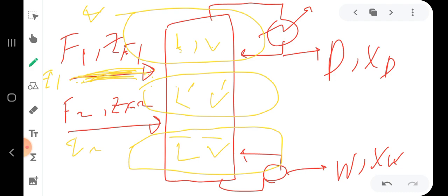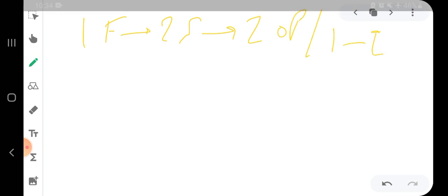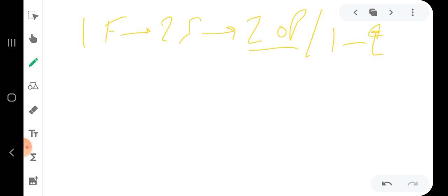And how are we gonna deal with this problem, and how are we gonna use the McCabe-Thiele method in order to analyze this type of distillation column? The idea is simple. Remember before, when we have one feed, we have 2 sections, so we have 2 operating lines and we have 1 q line, right? That change, we have 2 operating lines, one for the top section and one for the bottom section, right?